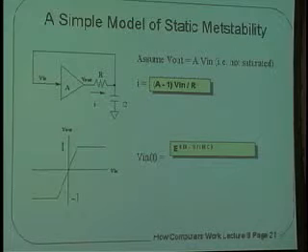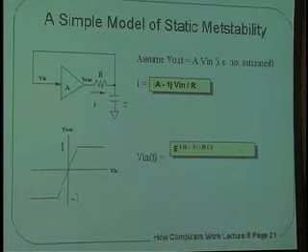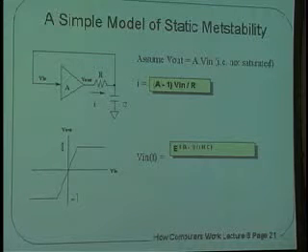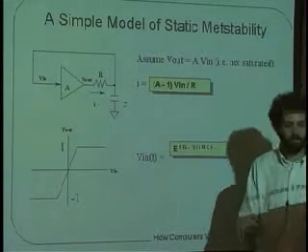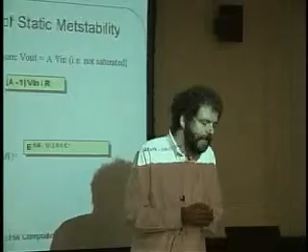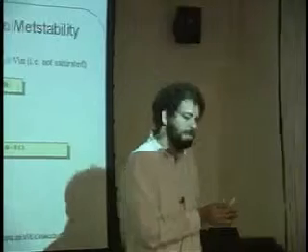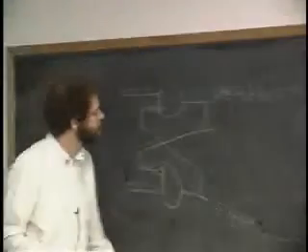Basically, what's going on here is we have this amplifier A, and we have a resistor and a capacitor which act to slow down or give some momentum to the circuit. The same way we have a donkey with some mass to it, okay? And it is attracted to one bale of hay or the other with an attraction that's proportional to how close it is to the bale of hay. If it's in the middle, it doesn't know what to do, but the closer it gets to one side, the more it's attracted towards there. Now, it has some mass to it, so it doesn't instantly go over there. It takes some time, but you might imagine that it walks faster and faster as it goes towards the end.